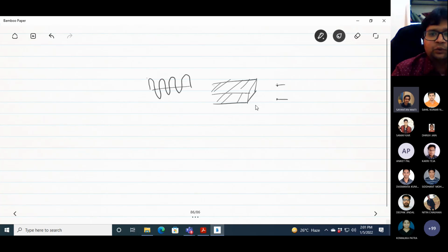You may argue that you can measure with respect to some ground potential, by creating a universal ground. In that case also, you will not exactly be able to measure the voltage. Another reason is that a very high frequency signal is a function of space. For example, say you have a transmission line. In circuit theory, whatever the voltage here, let's say V1, the same voltage appears there.